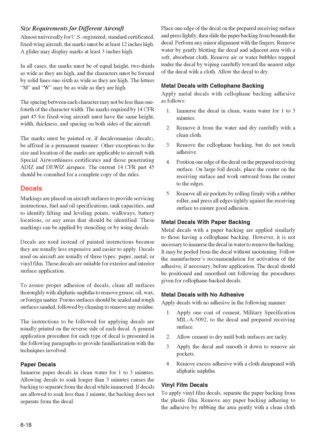A general application procedure for each type of decal is presented in the following paragraphs to provide familiarization with the techniques involved. Paper decals. Immerse paper decals in clean water for 1 to 3 minutes. Allowing decals to soak longer than 3 minutes causes the backing to separate from the decal while immersed. If decals are allowed to soak less than 1 minute, the backing does not separate from the decal.